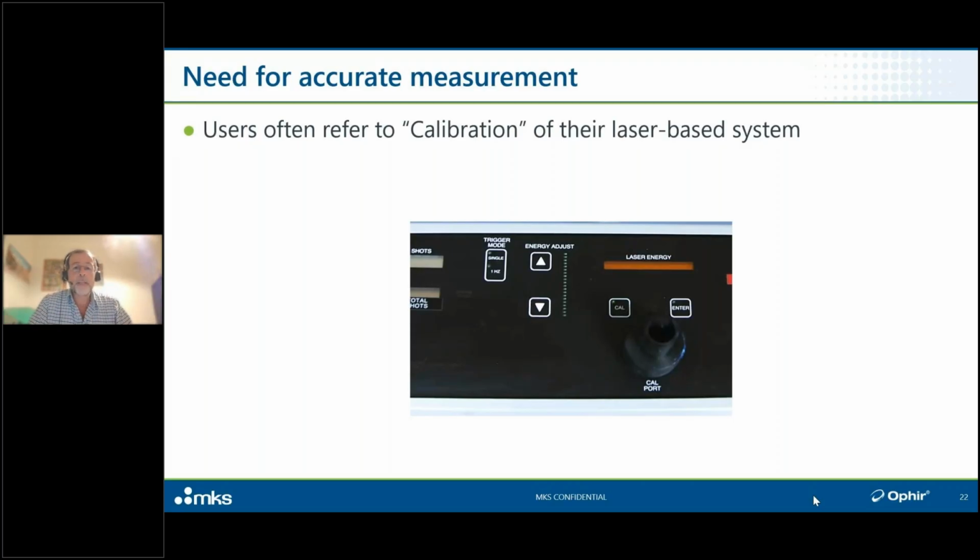But then what they do is they have an opening in one of the side panels of the machine, and there's a larger full-blown laser power meter that measures the full power of the beam. Let's say it's a surgical system, the user, the doctor, will once a day, once a week, before each procedure, whatever the needs are, take the handpiece, stick it into that hole, fire the laser once, and the system will compare what it's really measuring to what that monitoring detector thinks the power is, and if it needs to make any internal adjustments, it does so. It's a very neat solution that we've come across quite often.